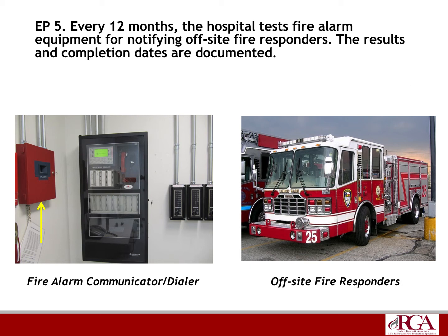The purpose of this is to verify that the monitoring station is receiving the proper signals in a timely manner. So they'll test fire alarm signal, supervisory signal, and a trouble signal. And that signal has to be received by the monitoring station and dispatched to the local fire department within 90 seconds. So when they're testing this needs to be documented appropriately. You need to have at least one trouble, one fire alarm, or one supervisory signal displayed with the time that it took to get that signal to the appropriate fire department.